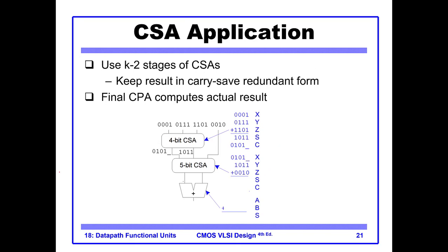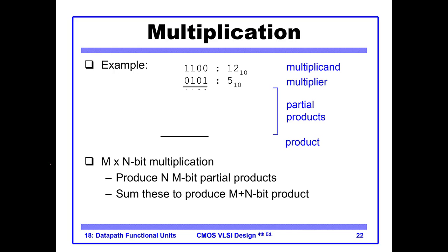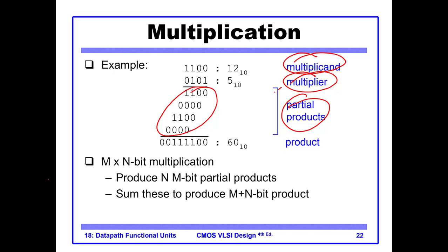Okay, so how this helps with the multiplication, that you can apply the carry save approach to the multi-input additions, and it will compress every 3 rows into 2 rows. So every 3 rows will be compressed into 2 rows, and then you combine the 2 rows and apply a carry propagate adder. So this is again multiplicand, multiplier, partial product generation, and these are your multi-input ANDs, and then you add. This is the final product.